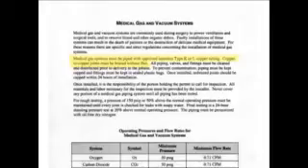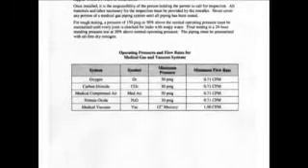Copper to copper joints must be brazed without flux. The reason for no flux is to avoid contamination of the pipe. Read through the next couple of paragraphs, and the chart on the bottom, go ahead and read through on your own, noting the differences and the requirements.